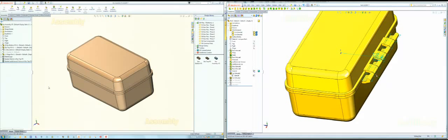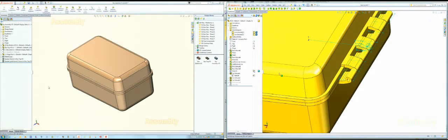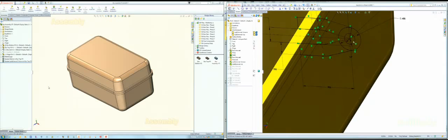So we've got our hinges, but we don't have a pin yet through it. Let's go back, and we're going to edit this sketch. And if you remember the sketch, not that sketch, this sketch. We edited this sketch, and I actually added the circle, and I actually did a cut with that circle to get rid of our excess material.